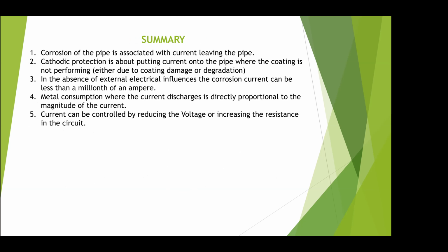And here's where the issue comes again with the coatings, because when I first started in coatings, there wasn't the wide variety or the high quality coatings available that there are now. And we only had two specifications, really. It had to be black, it was asphalt. And if it was really corrosive, it was thick and black. And that was all there was to it. There was no lovely three-layer polyethylenes, no lovely butylene tapes or anything like that.